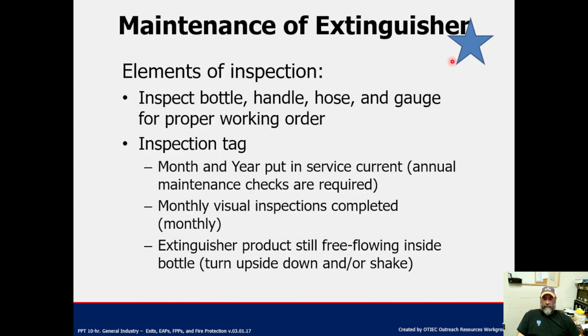Last thing here, and then there's just two picture slides that you can look at on your own. Extinguisher maintenance. One of the big things that is required is the annual maintenance checks, required per OSHA regulations. I think it's CFR 1910.157(e)(3), that is the requirement for the annual maintenance check of your fire extinguishers.